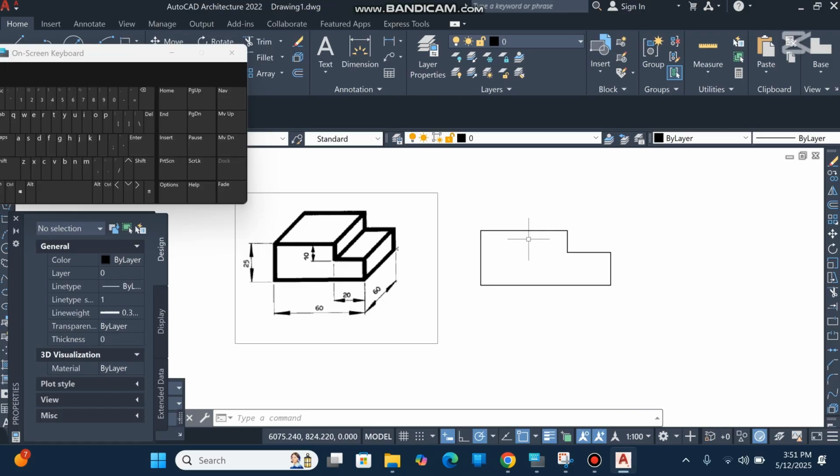For this drawing that I'm doing right now, we're doing Cavalier. Just like in the beginning of the video, I did say that with Cavalier, you just do the complete line, and with Cabinet, that's where you would cut the 45-degree line in half. So let's go. L, enter.